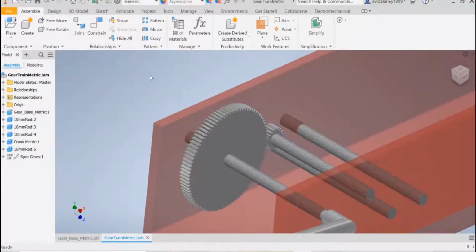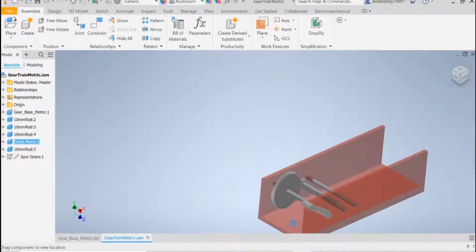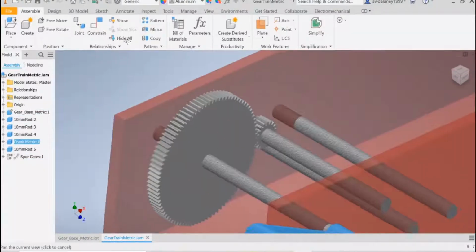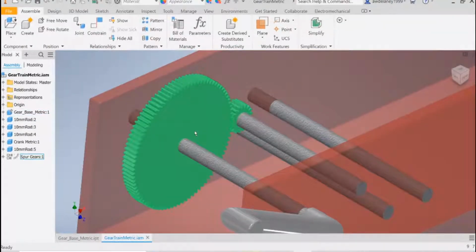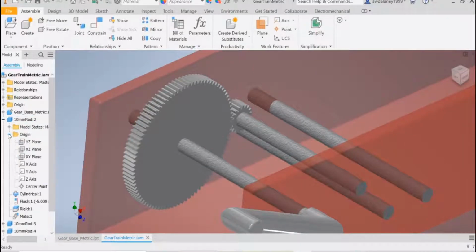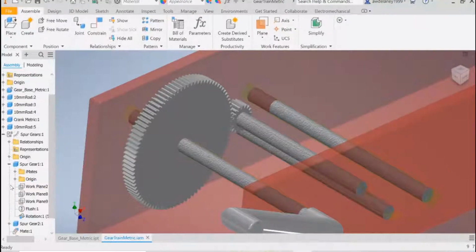So that only leaves us with 1 degree of issue, I guess, which is that this rotates separately from the gear. Now, how do we want to change that? Because there's not really any immediately obvious surfaces that we can use to constrain the axis of rotation with this axis so that they rotate together. So what we're going to do is we're actually going to go into the rods here. We're going to go into their origin, and we're going to select one of their origin planes. I'm going to turn on the visibility. And I'm going to do the same thing for our gear right here.